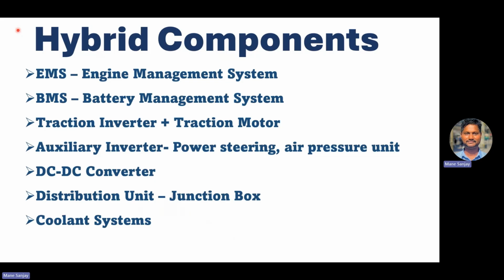Coolant systems are also very important. If your system works on a high power rating, then you need liquid cooling. If your system is lower power, then probably an air cooling system also works. For liquid cooling systems, we usually use water plus glycol, with a 50% water and 50% glycol mixture as the coolant. The benefit of glycol is its natural property that its temperature always remains low, and once we add it to the water, it increases the boiling point of the water.